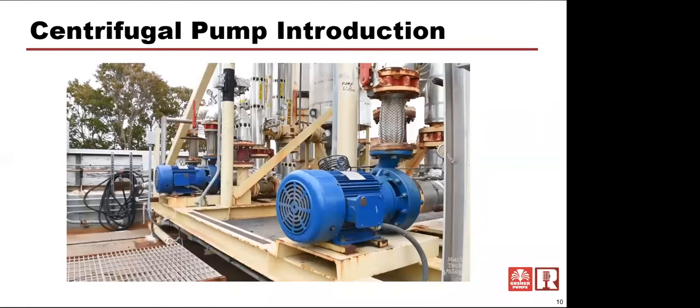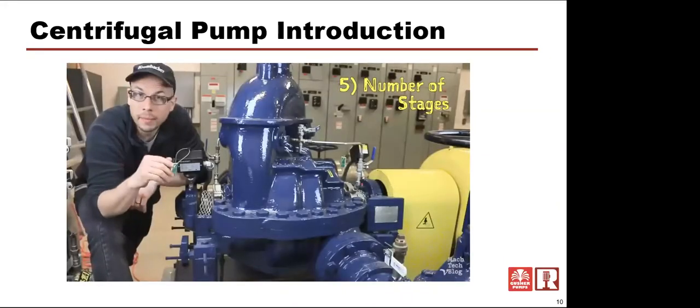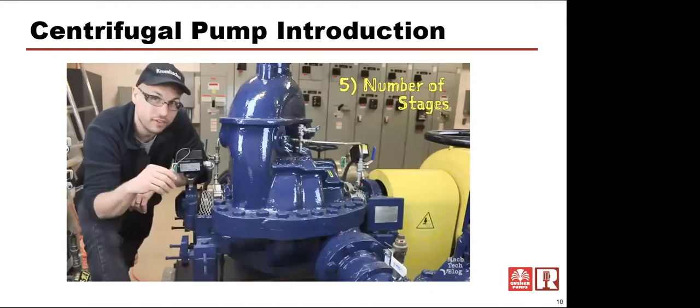However, since both the pump components and the driver components are supported on the same shaft just by the bearings in the driver, this mounting method is really only appropriate for small and medium-sized end suction pumps. Finally, a pump can be classified by how many stages it has.